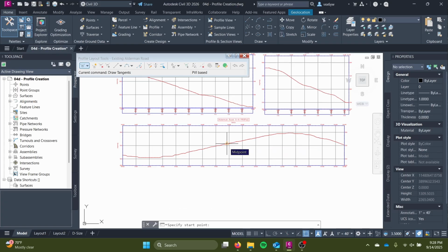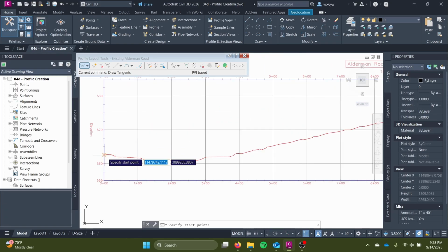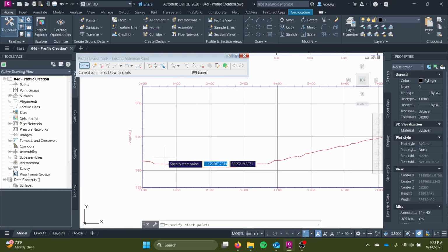Now, when you think about making a road, there's a couple things to keep in mind. One is that you want your grade to be about 4% or less. You don't want it to be above that unless you have a really steep mountain climb or something. And that's especially true for heavy duty trucks and cargo. The grade can make a big difference for them.